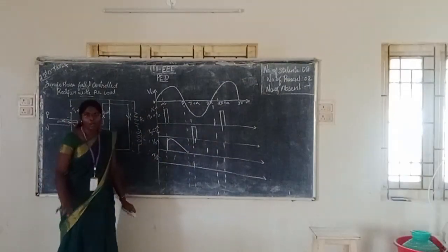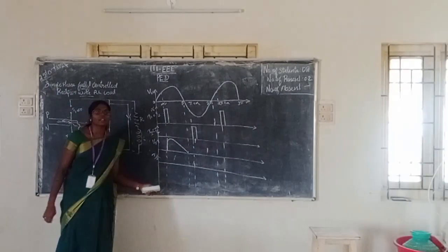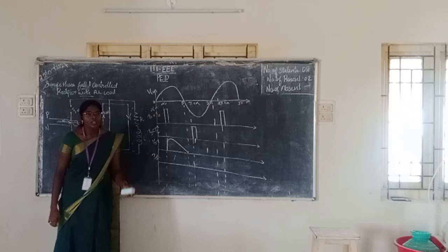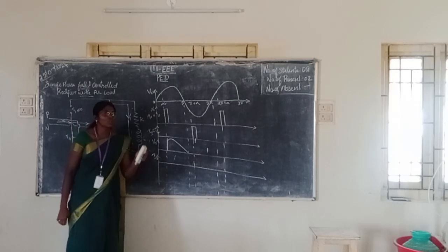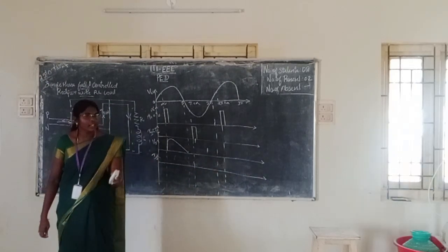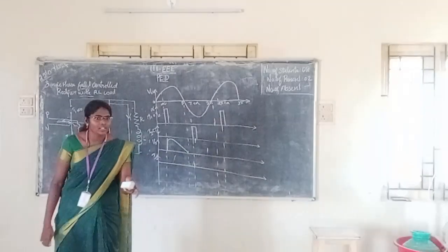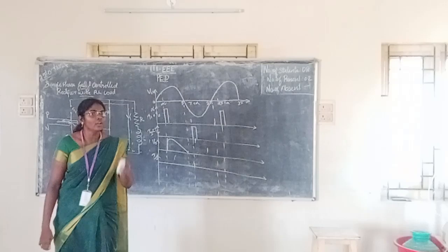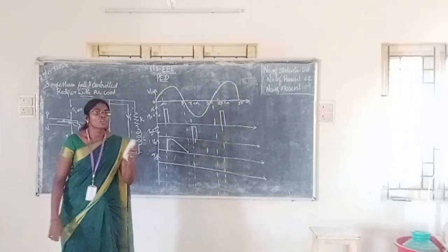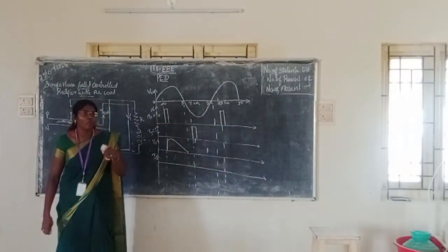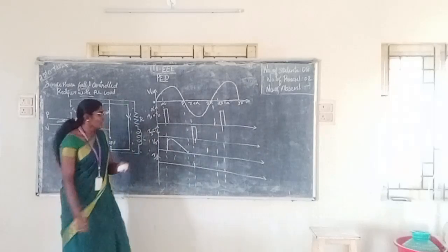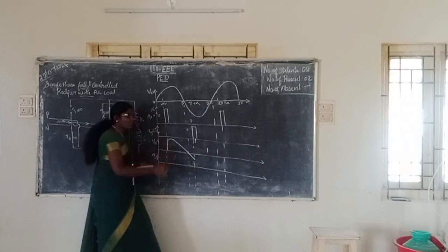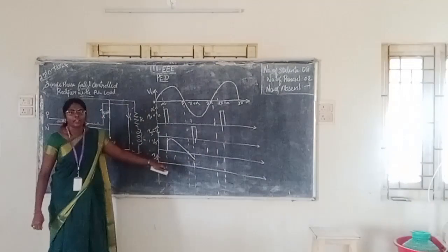This is similar to R1. And here, what is there in the circuit? An inductive nature is there. The inductance will store some energy. So after reaching 0, what happens? The inductor will release its stored energy, because there is no supply voltage there. Due to that, there will be a flow of voltage in the reverse bias condition. So under that condition, the output load voltage will go to the negative side.